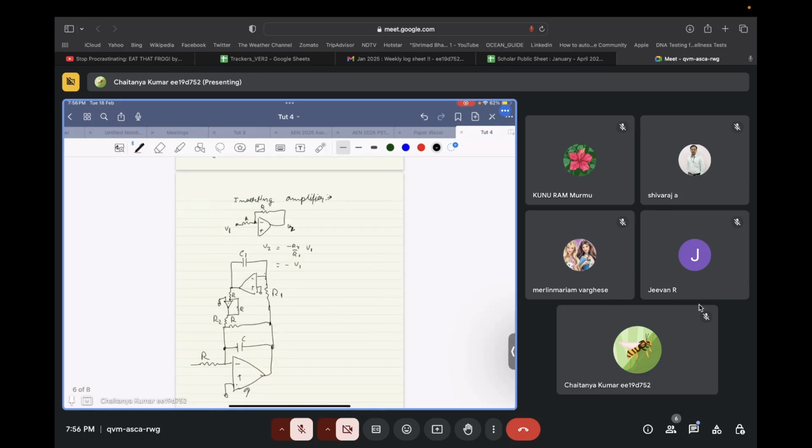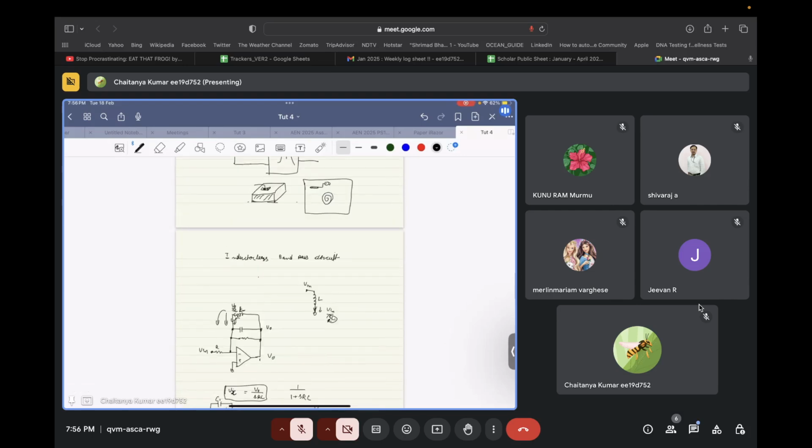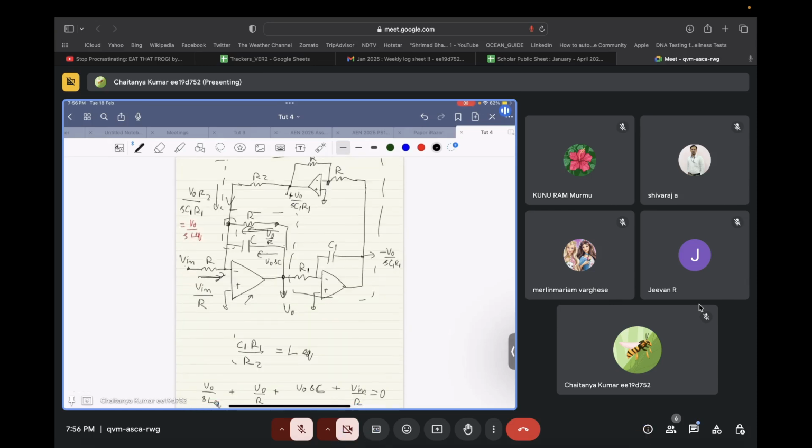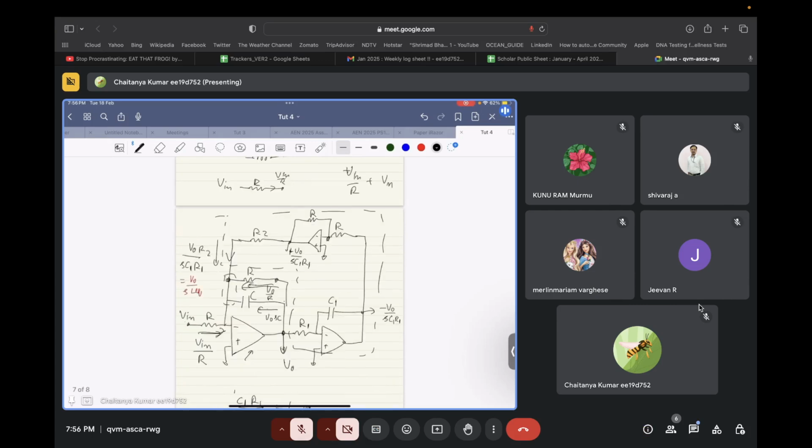So in the above circuit, when there was only RLC over here, there were two resistors, right? So the amount of noise that was getting generated was small. But in this case, how many do you have? 1, 2, 3, 4 resistors and 5, 6. 6 resistors are there. So the number of noise generating elements has increased by 4 times. The number of power consuming elements has increased by some 3 times. So there are definitely problems that you need to deal with.